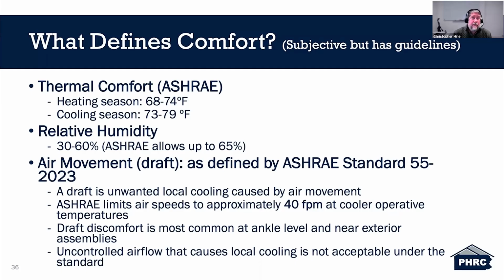I would be very careful, and I would check if you're installing specific finishes, and I'm going to touch on hardwood floor just a little bit here. A lot of hardwood floor manufacturers specify what your relative humidity must maintain at or not exceed for their product warranty to be valid. And that's not necessarily for just the area in which that product was installed. It also has to do with the space below it as well. So a basement, for instance.